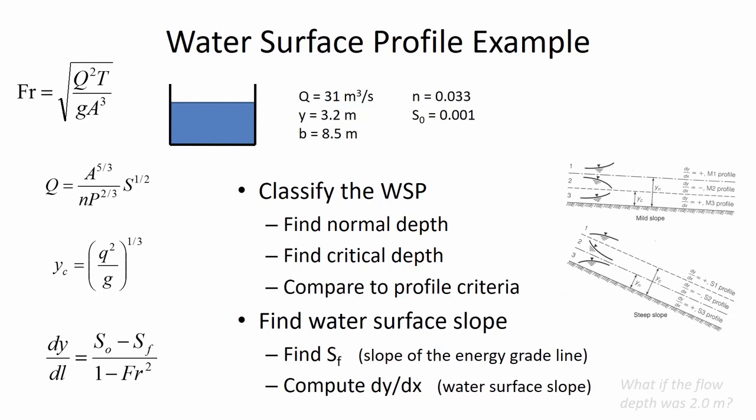So let me refresh your memory about here. We've got a stream, and the water depth maybe is getting deeper as it approaches some sort of an obstacle, maybe an underflow gate where the water is continuing on. And so if we found the slope at a certain location and we just extend linearly, then the actual depth some distance downstream, if we said here's our delta x, and we just applied the process equation directly, it would underestimate the depth downstream.